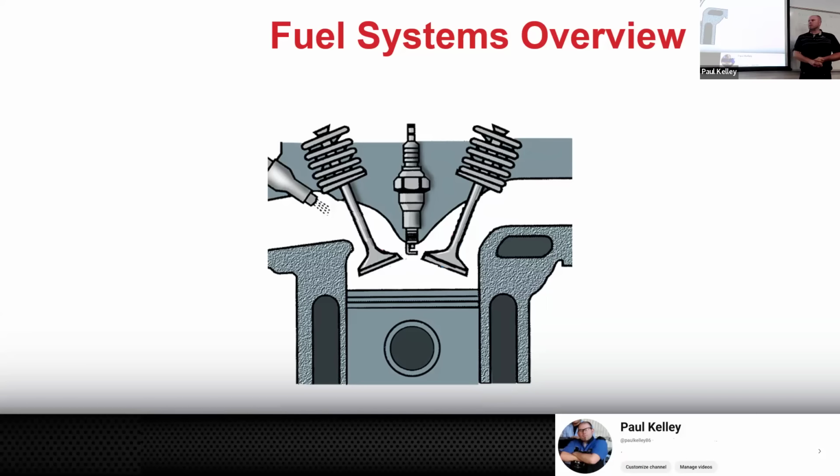What if your fuel pump, you're expecting to make 55 psi, but it's only delivering like 30? What do you think might happen? It's going to spray fuel, right? But do you think it's going to spray enough fuel? Probably not. It may start, but then you try to accelerate. When you accelerate, you need a bigger volume of fuel, and if your fuel pump can't keep up, you're going to be